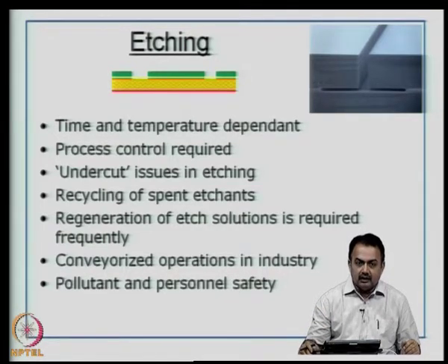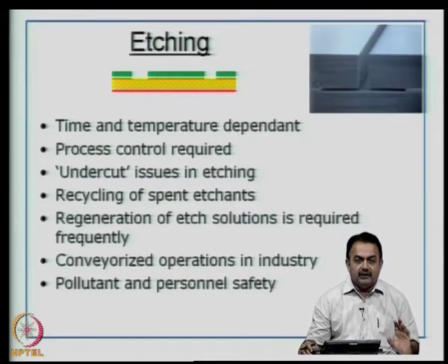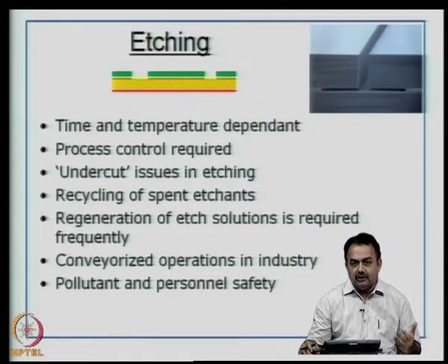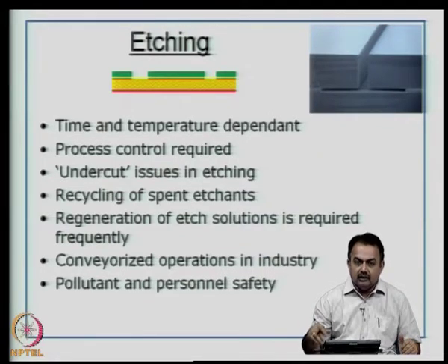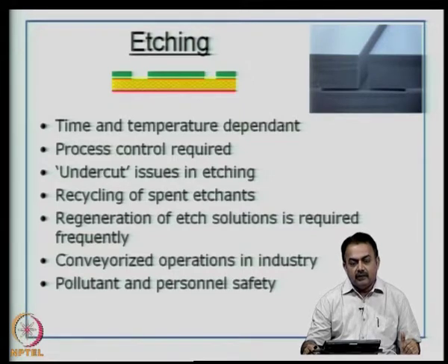Therefore, you need to monitor regularly the concentration of the copper that goes into the solution, because the basic reaction of an etchant with the copper surface on the PCB is that the copper has to dissolve into the etchant. Therefore, as the copper concentration increases in the etchant, your reaction slows down, the rate of etching goes down, and therefore your etch time, which is actually a very key factor in large volume manufacturing, will increase, which will again indirectly show up in the undercut.